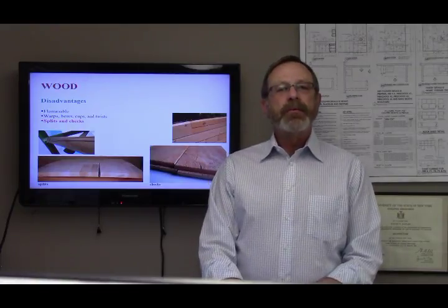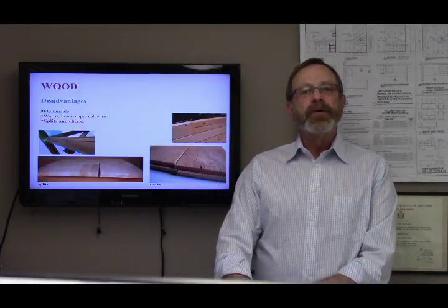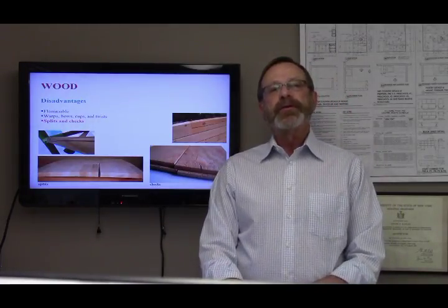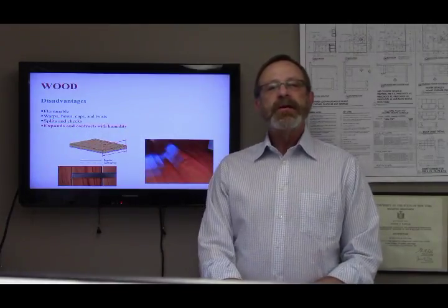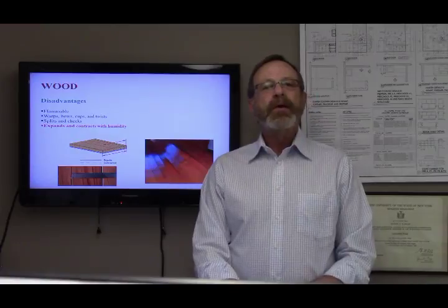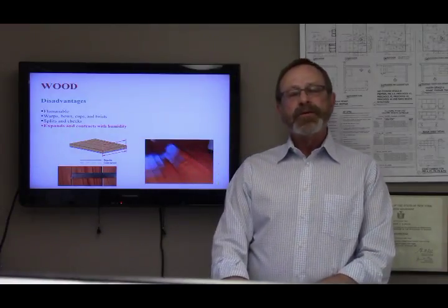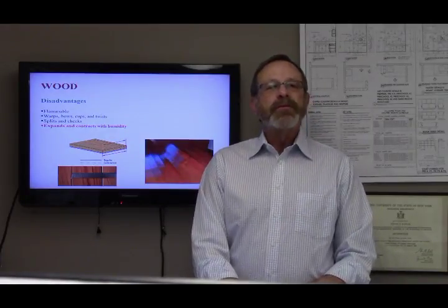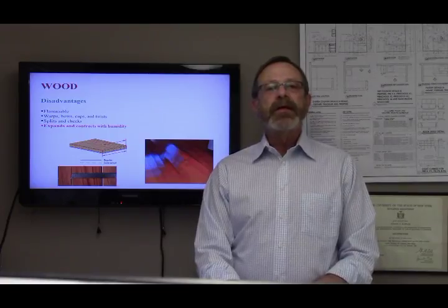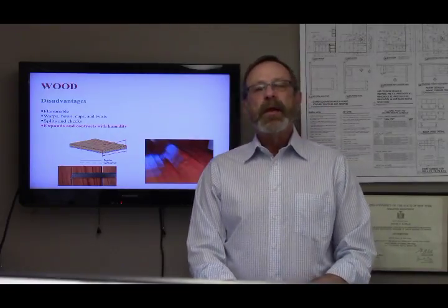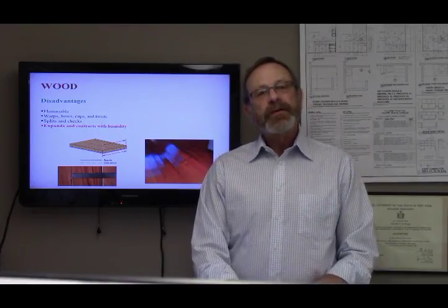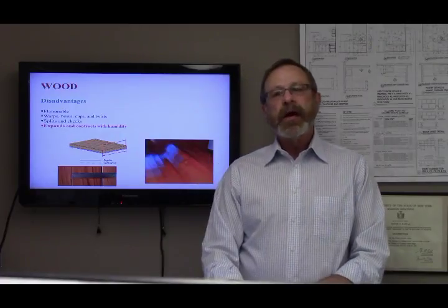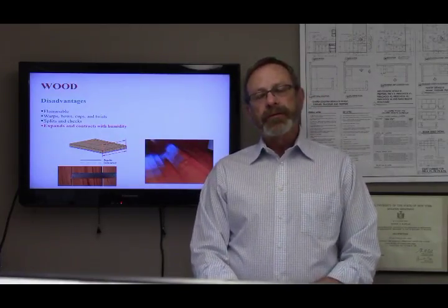Splits and cracks are ruptures or separations in the grain of the wood which reduce the quality as measured by appearance, strength, and usefulness. The dimensional changes that accompany the shrinking and swelling of wood are major sources of both visual and structural problems. Shrinking and swelling occur as the wood changes moisture content in response to daily as well as seasonal changes in the relative humidity of the atmosphere. When air is humid, wood absorbs moisture and swells. When the air is dry, wood loses moisture and shrinks.